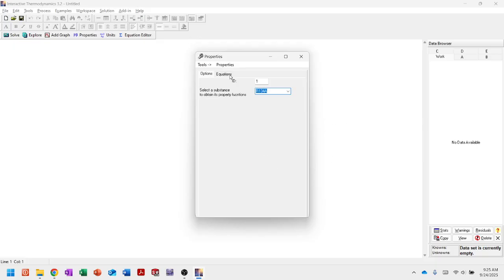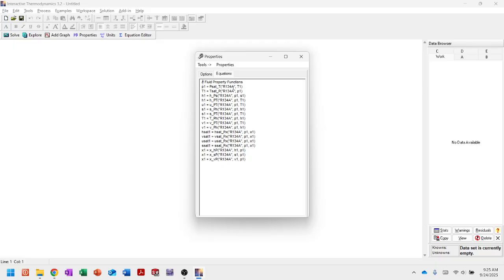First off, I know the pressure and I know the volume, so let's put a few of those in before we even get there. So P1 is 100 psi. V, I'll make a capital V, is 20 cubic feet, and our M is 75 pounds. So V1 is going to be V divided by M. V2 is also that same thing. So we have our specific volumes, and we have our pressure at the beginning.